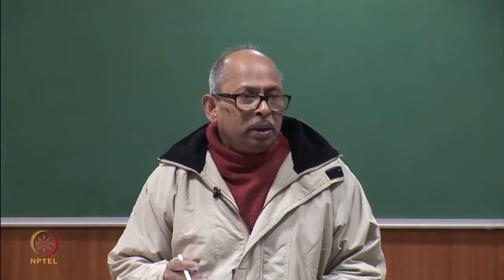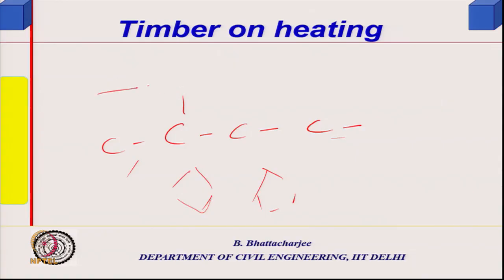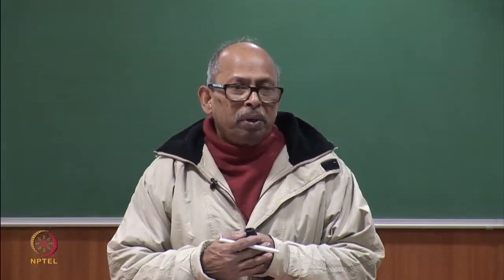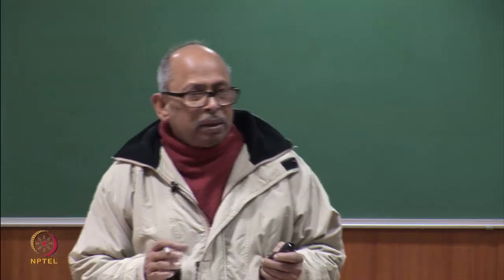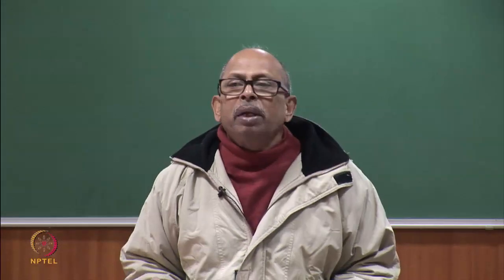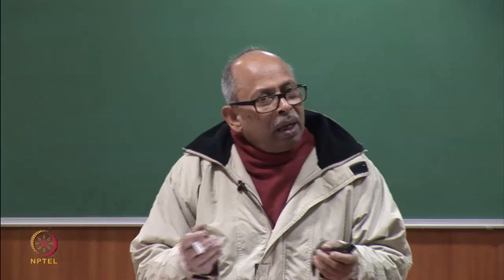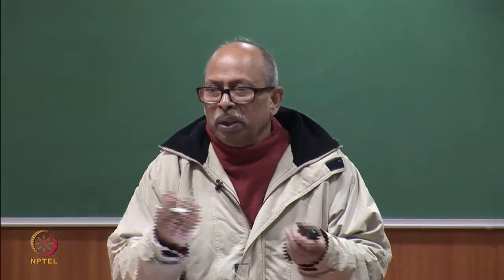These are called thermoplastics. Now, supposing I have a 2-dimensional structure instead, then sliding is not possible, and if it is a 3-dimensional structure, sliding will further not be possible. So, complex 3-dimensional structures where such sliding does not occur are called thermosets. You can heat them up, but the molecules will break, pyrolysis would occur, and if you still heat to the ignition temperature, smaller molecules will come and can react with oxygen, a combustion process.